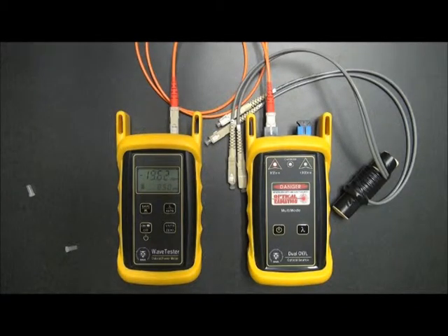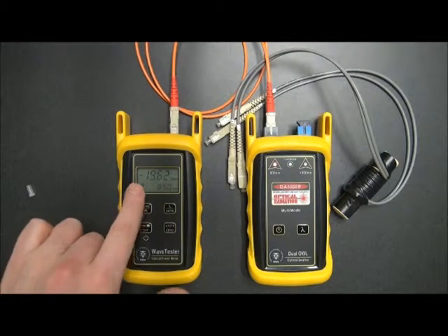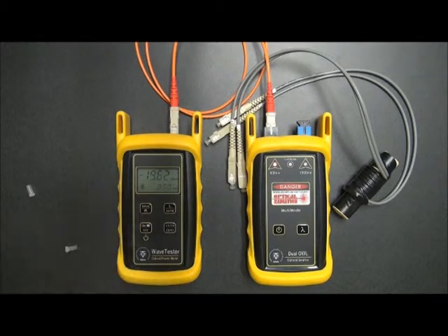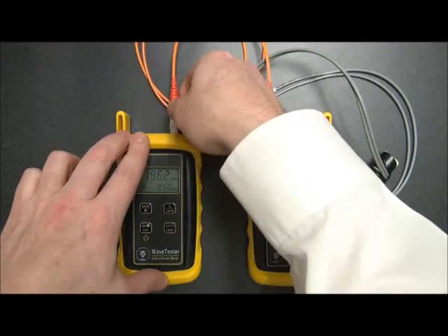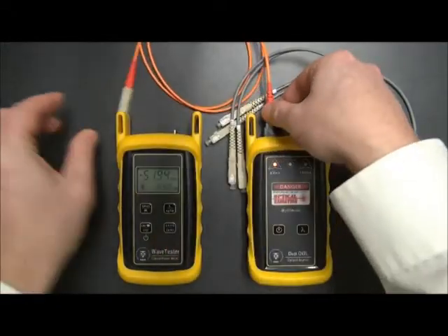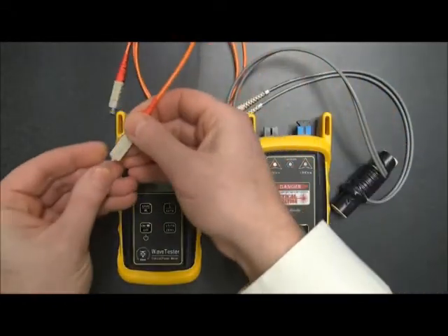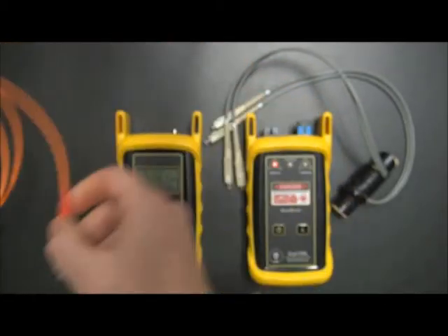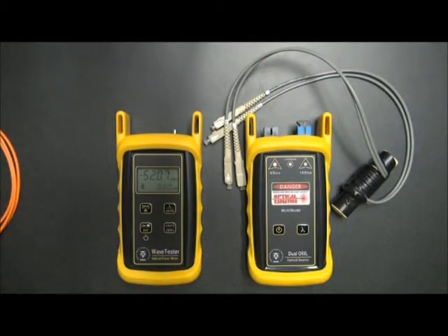Now, as you can see here, we have a reading of minus 19.62 dBm. Okay, now this is good. We expect this patch cable to be reading at around this power level. It's a little higher than minus 20, and it's not mandrel wrapped, so it's going to be a little bit higher than our calibration level. So what we know now is that this orange cable here is okay to use. So what we'll do is remove it from the testers, and we will set it aside because we won't need it until we start taking measurements.